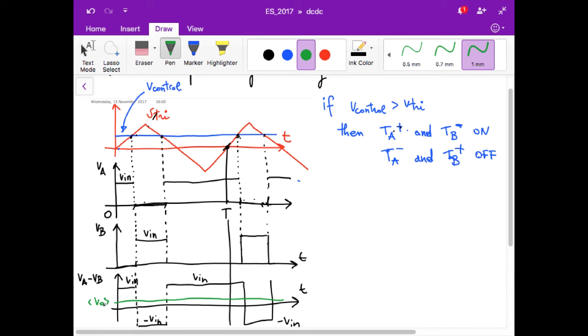This is what is typically done, because in practice the mechanical part behaves as a low-pass filter, and therefore filters out all the harmonics of the signal and only retains the DC term. So there is an effective filter done by the mechanical part in movement.